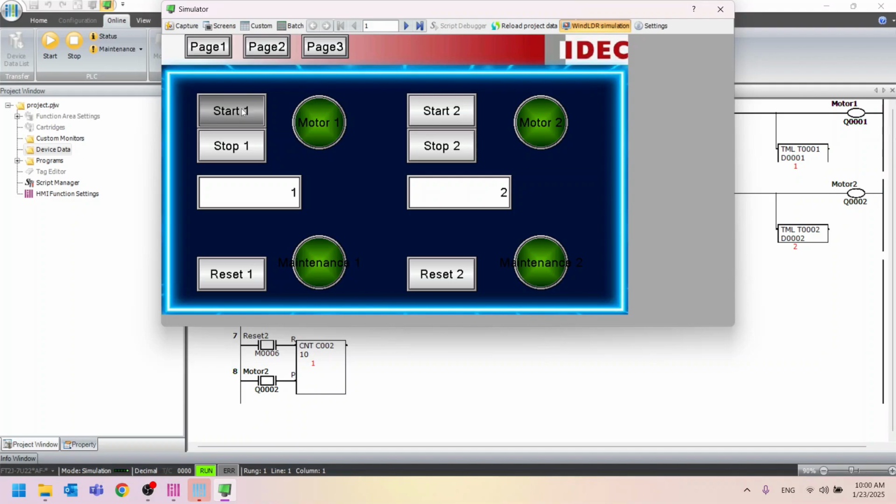You'll notice that the lamp does not turn on. The reason the maintenance lamp doesn't turn on is that I haven't written the output for this lamp in my PLC program yet. This shows how simulation can help you identify errors in your program before using it in a real application. Next, close the simulation and click OK.